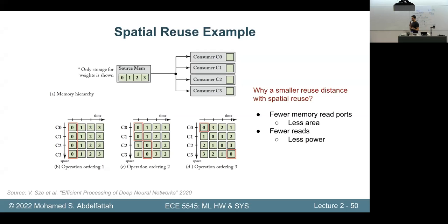So memory ports just mean a port from which you read memory, right? Here, this illustration is showing a single memory port. There's one wire coming out of this memory, but I can have 4 of them, right? But each memory port costs actually quite a lot. It's not just a matter of adding a wire, it's a matter of replicating the memory and being able to add all the addressing logic and so on.